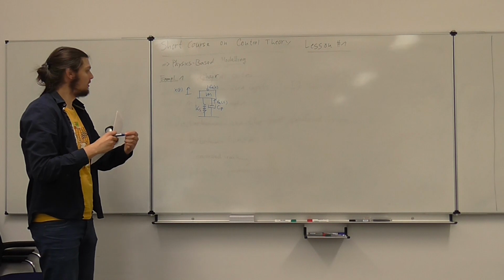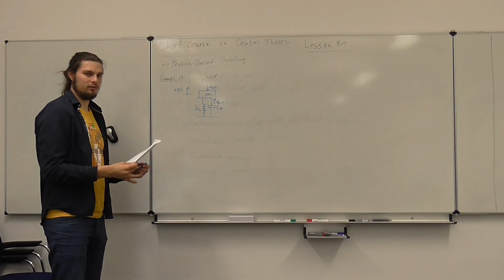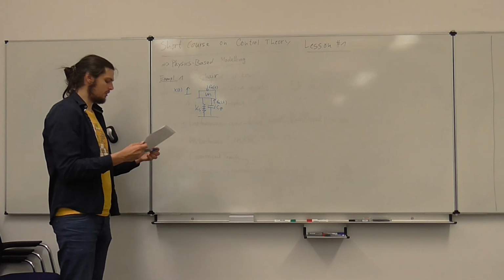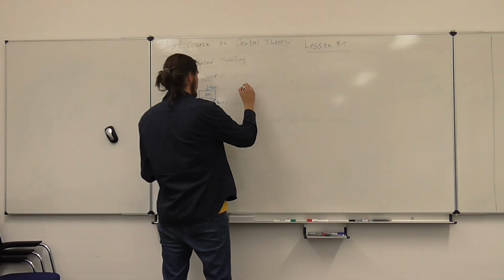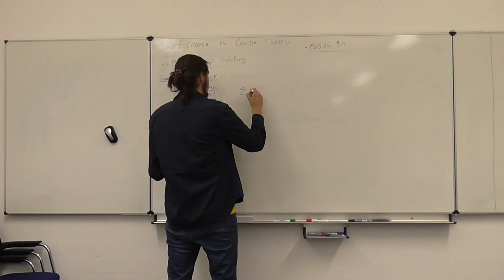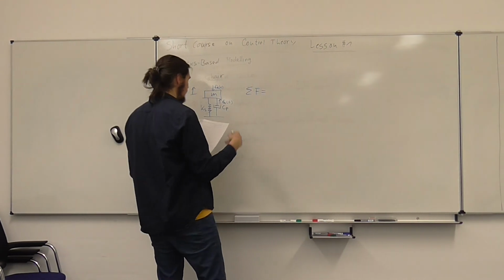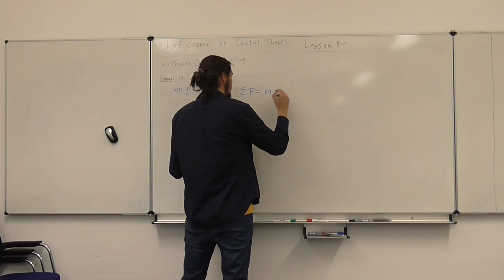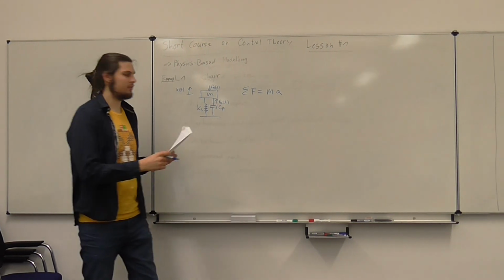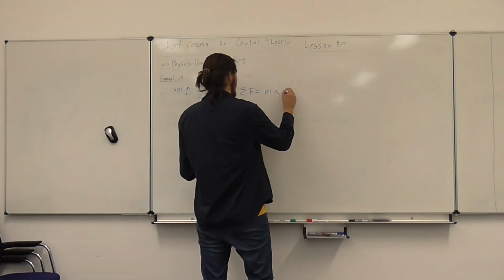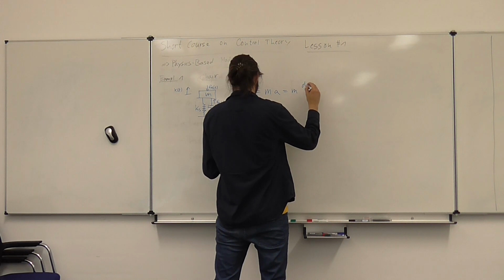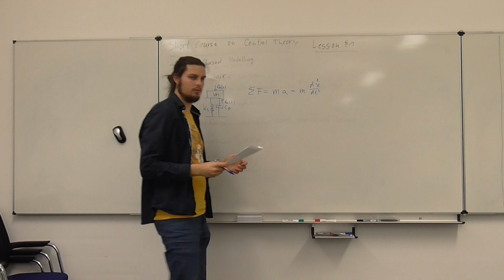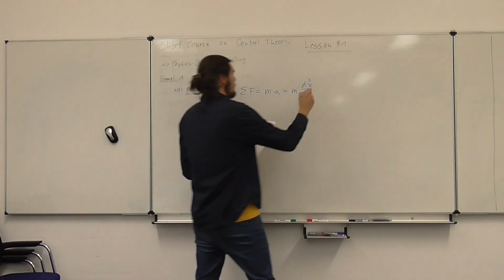And now we try to start with the modeling. First of all, always a differential equation, right? That's the first thing that we start with. And here we can use Newton's law that the sum of the forces will equal M times A, correct? Which means that this is M d²x(t)/dt², correct?